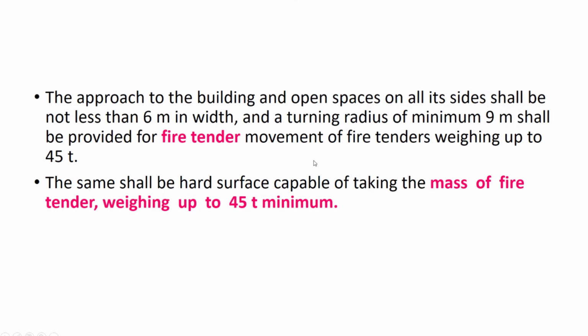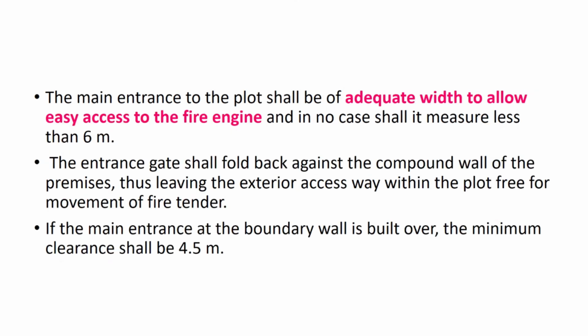That means there are multiple buildings. There are 2 or 3 buildings coming up in the same area. Or a multi-storied building of the structure height less than or equal to 50 meters. So in all these provisions they are saying the boreholes in a grid pattern with a point at not more than 50 meters distance, subject to a minimum of 2 boreholes, and boreholes should cover the built up areas.